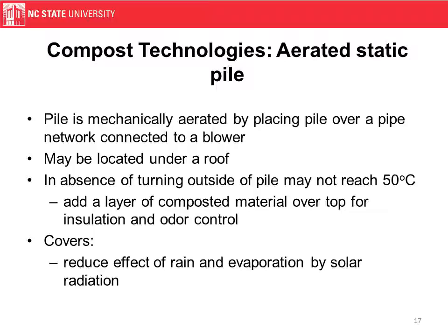The static pile in this case just meaning that it's a pile of material that's really not turned in the same way that windrows are, and aerated meaning that there's pipes with a blower underneath the pile that provide airflow through the pile. Sometimes these are located inside, sometimes outside, and a lot of times it is common for a finished compost product to be placed over the pile, providing a layer of insulation, and it helps with odor control as well.